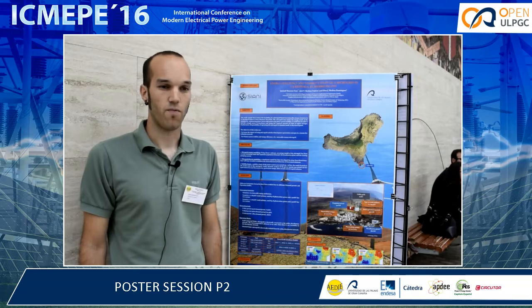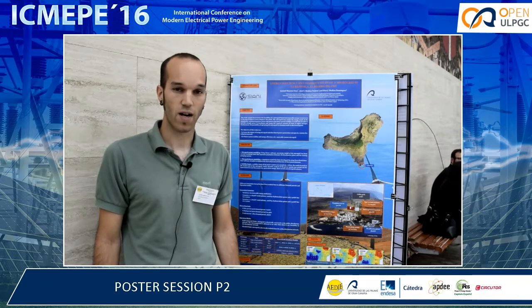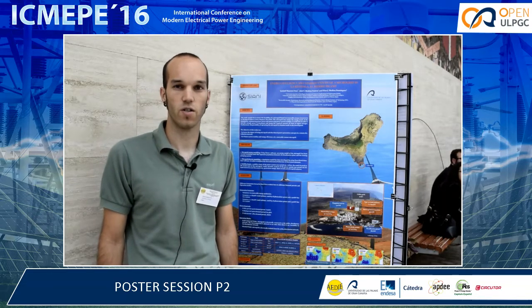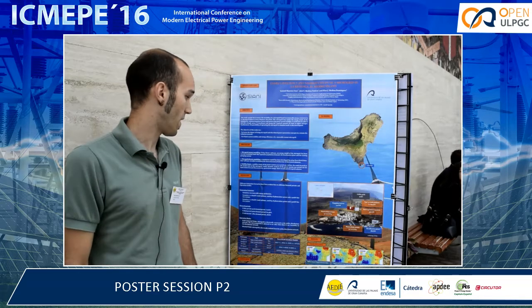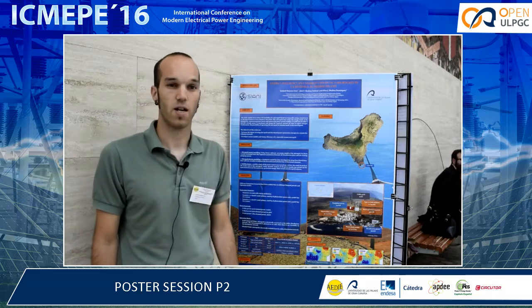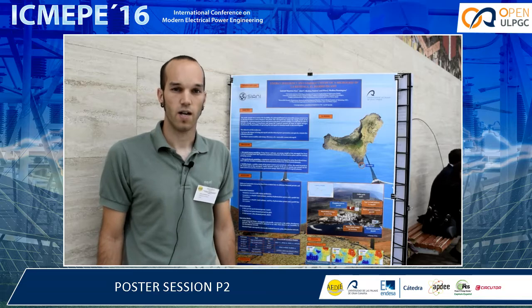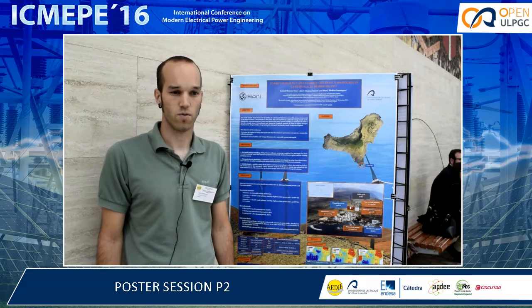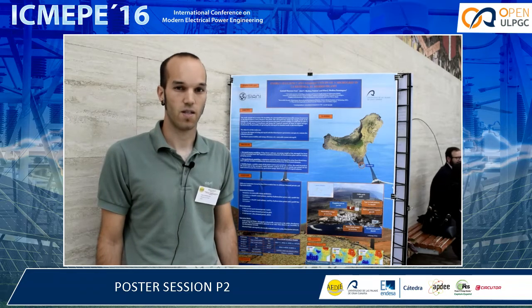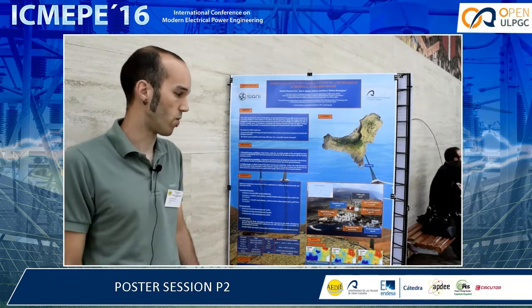and we have tried to assess the impact of concepts like microgrid and distributed generation in a remote town. First of all, we have made an energy model using Homer software, and we have found the best combination of generation that leads to a lower energy cost. And after that, we have built our electrodynamical model using PowerFactory simulator, and we have performed a stability study to assess the efficiency and the stability aspects of this proposal.